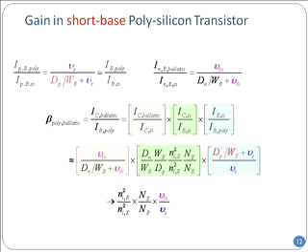Now, does this go with what I had been saying before? Before, the diffusion coefficient for the electron, D over W_B, when W_B was large, was a small quantity compared to V thermal in the first term, in the magenta one. So generally in the long base transistors, you drop D over W_B. If you drop that one, then V thermal in the numerator, V thermal in the denominator, so that will give you 1. And that is the standard transistor.